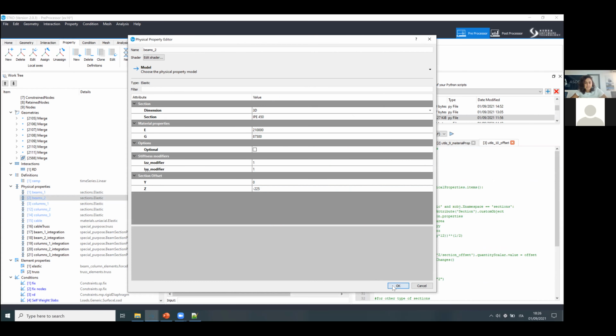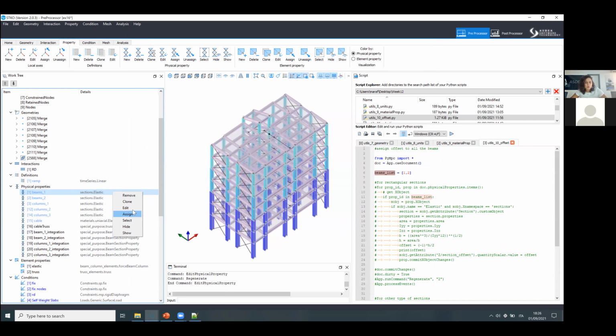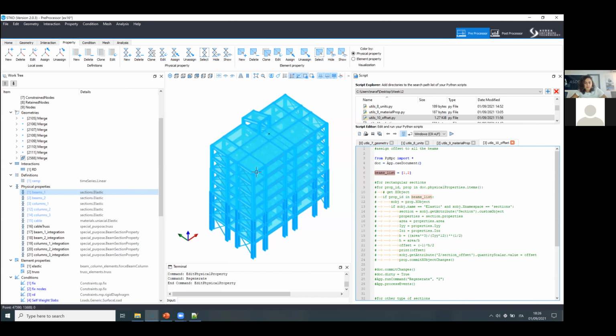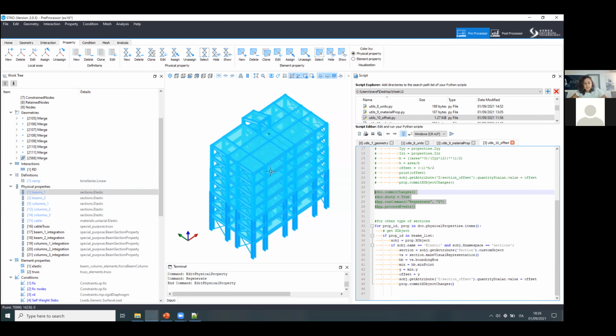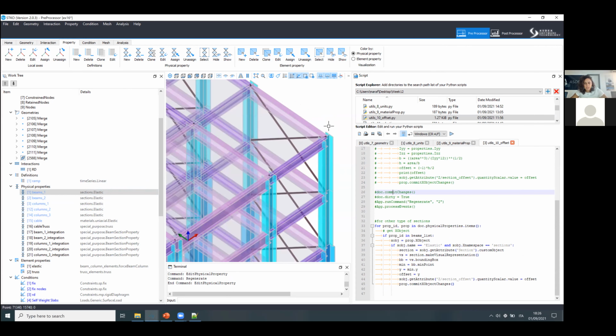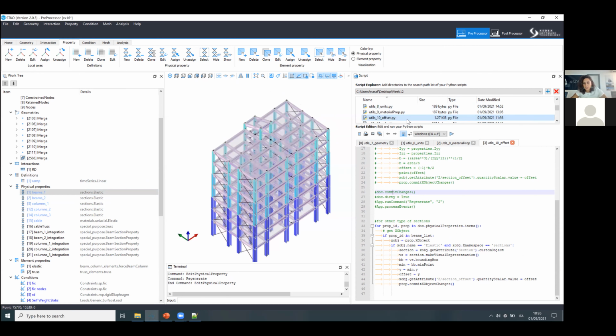Yeah, so this has been assigned. And as you regenerate the view, or just use the command, this one, regenerate the view, that was not copy pasted at the bottom. If you regenerate the view, then you will have the offset assigned to your section. So this is just a quick trick that you can use.